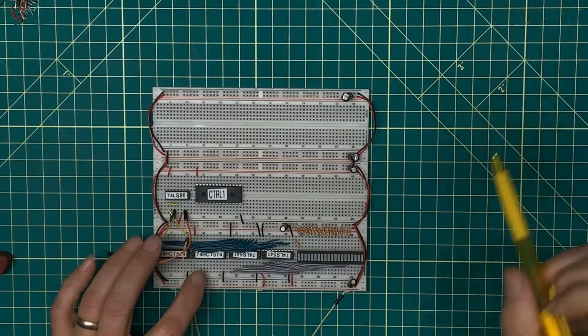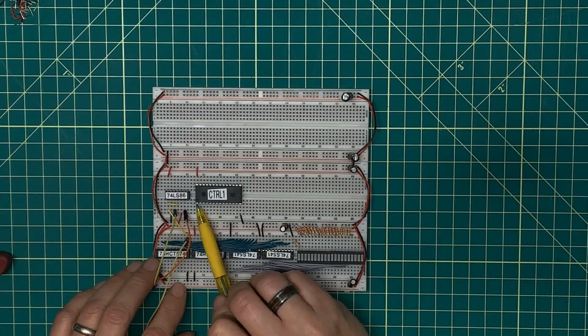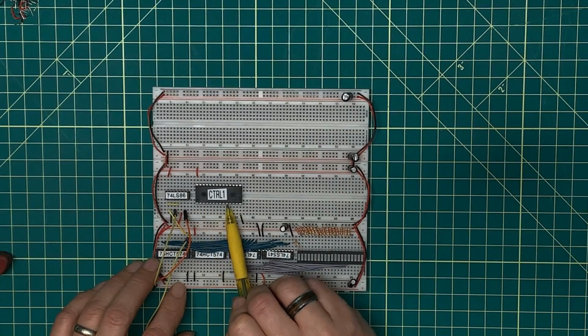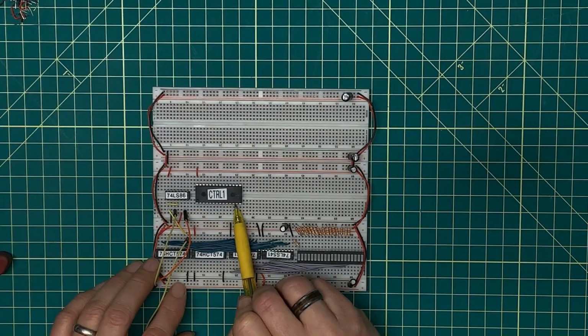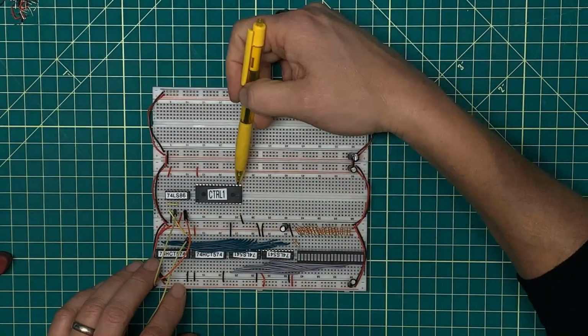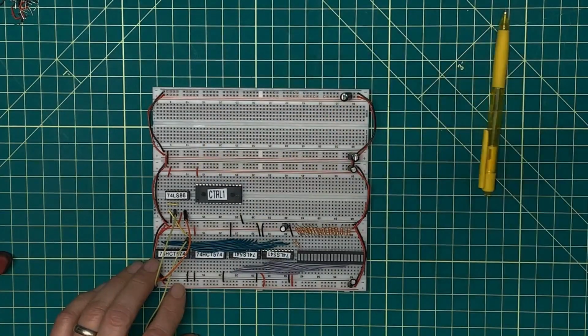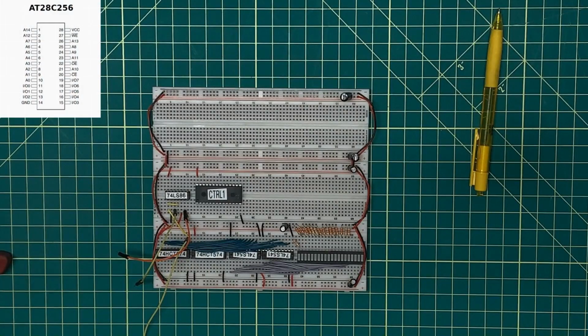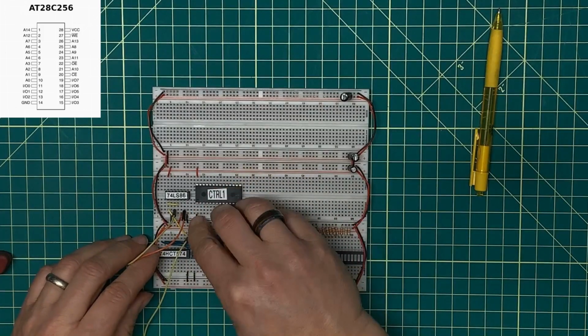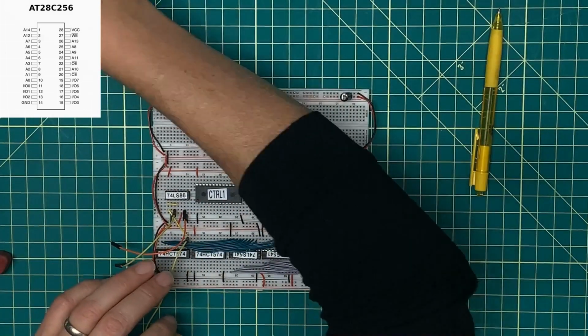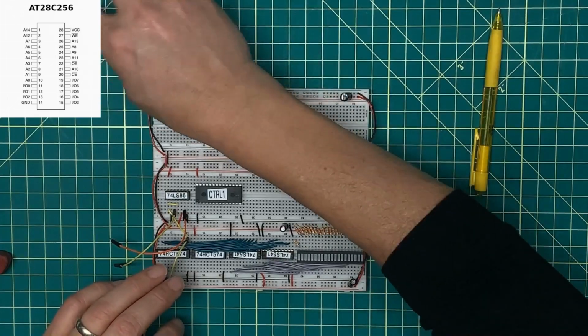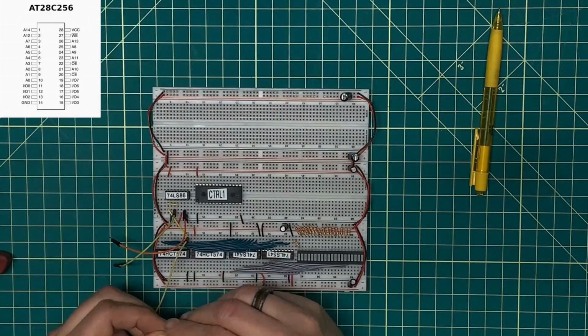Now I know that these two are address lines that we don't want to use. There's 8 address lines in a row here. 3 input-output lines, which I'm only going to use for output, plus 5 more up here. And then the rest of the control lines and address lines sit up here. And I will put a schematic up at the top of the screen for you to follow along as well. Pin 1 is address line 14, and I'm not going to use that today. Pin 2 is address line 12, and I'm not going to use that today.